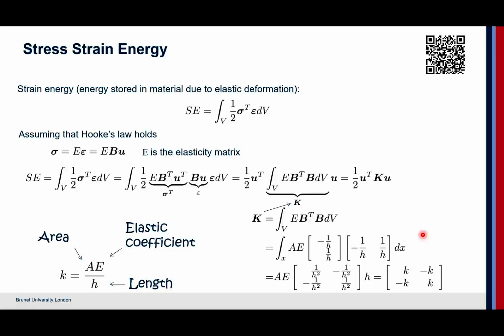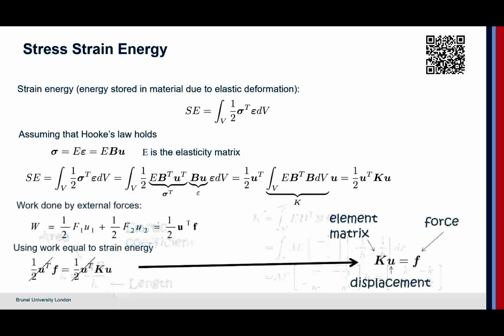When you come to the literature and you see various expressions for springs and masses, for energy, strain energy, or minimization principle, you can show that they are all related. If you can bother to work through this, it's essentially a process of strain energy being equal to stress times strain, substituting in the expressions for stress and strain, and cancelling coefficients. You end up with the equation in terms of spring constants, where these spring constants are just the area times the material coefficient over h, and actually the equation you end up with is just 1 over h.